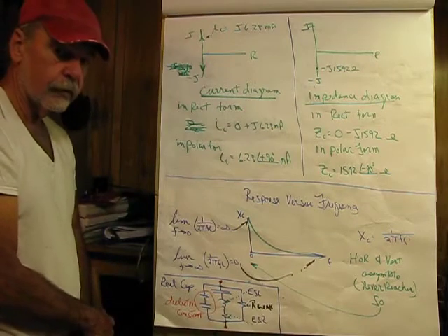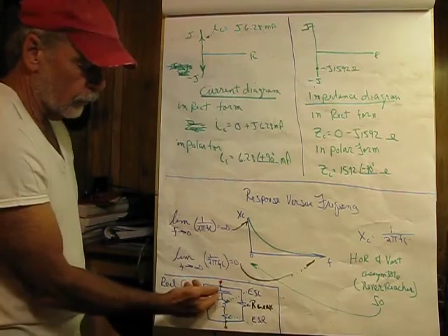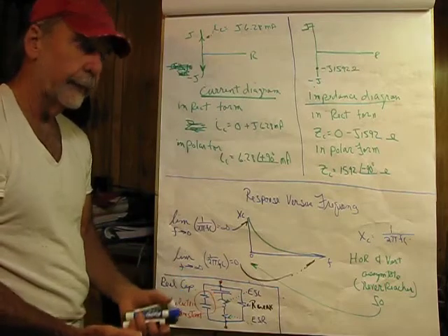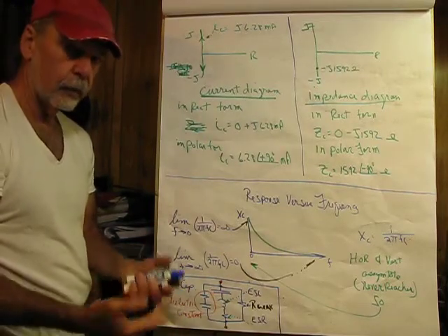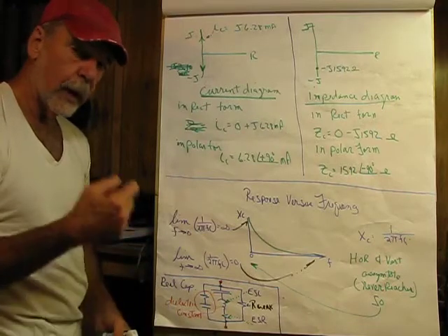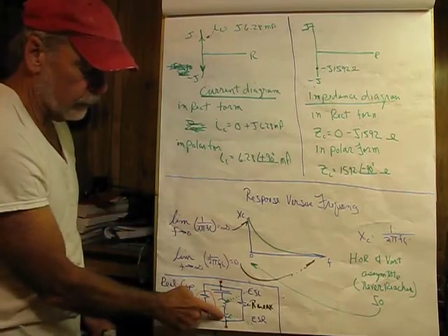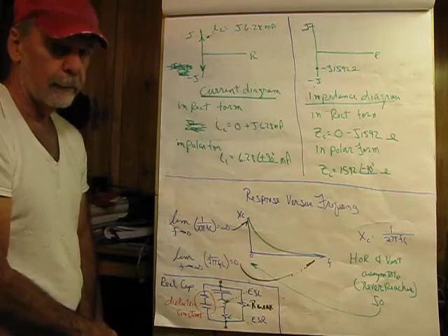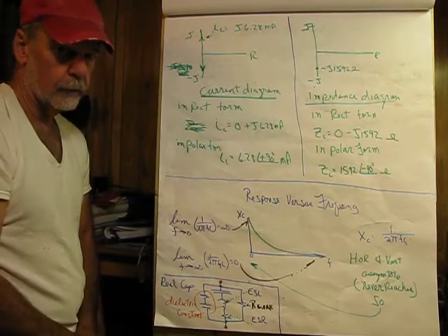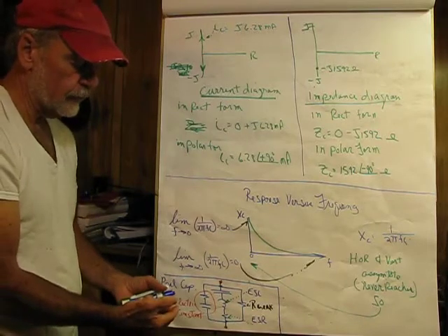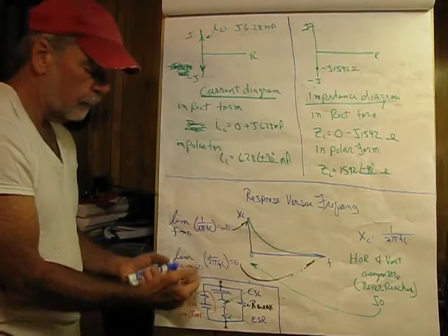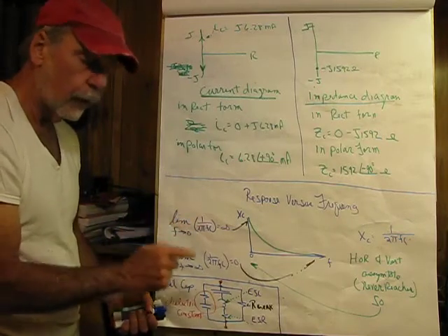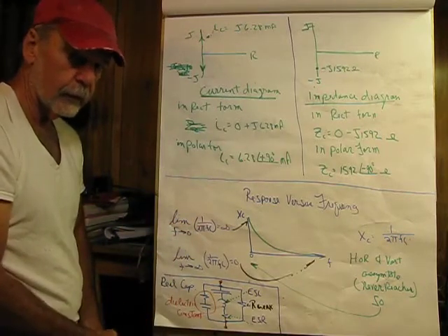We also have a component called ESR. That's effective series resistance. So if you're replacing a capacitor in a switch mode power supply, like in a TV set, a computer power supply, or whatever, you have to use a capacitor with a low ESR, or the switch mode circuit will eat the capacitor. They cost more, and in some cases manufacturers of the ICs that build the switchers will tell you manufacturers and part numbers to use. It's that critical.